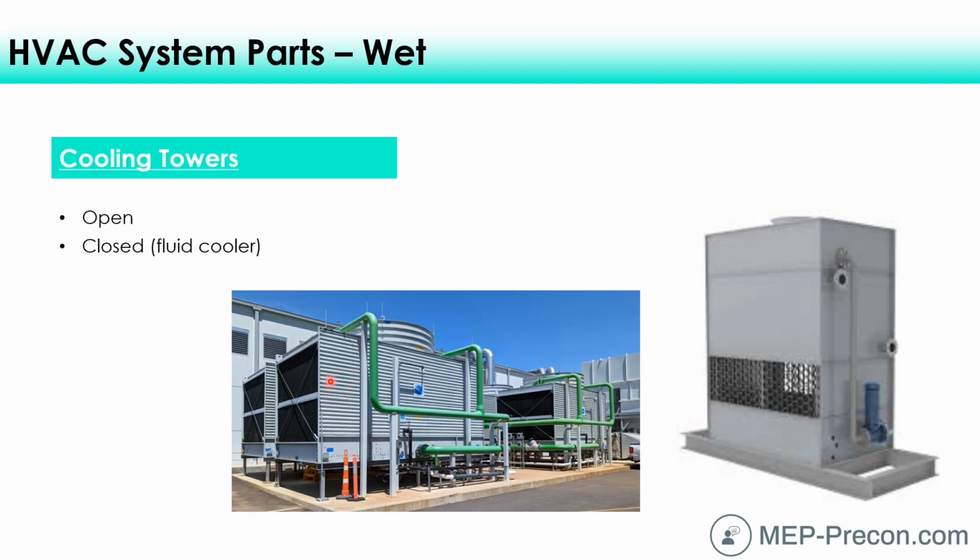And so what that means is that water that falls to the sump here and gets collected within this big sump and returns back to the chiller into the pump, that could contain a lot of contaminants. It could be leaves, it could be cigarette butts, it could be dust, who knows. Now there's filters within here, it's called a strainer. We can strain out most of that stuff, but it's a maintenance thing. We've got to clean out that strainer every so often because it's going to have a lot of just things from the atmosphere floating or getting into that sump.